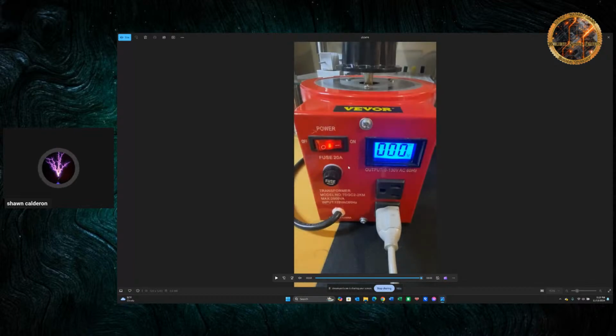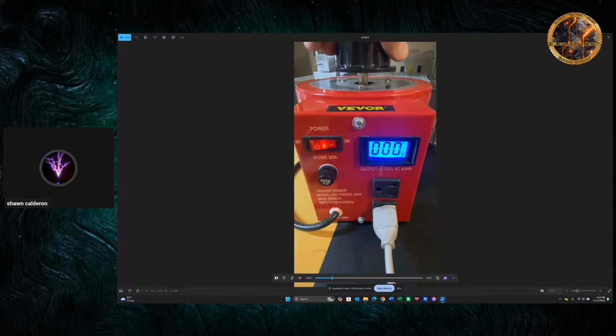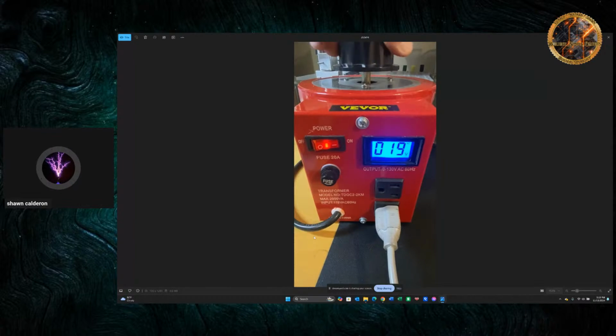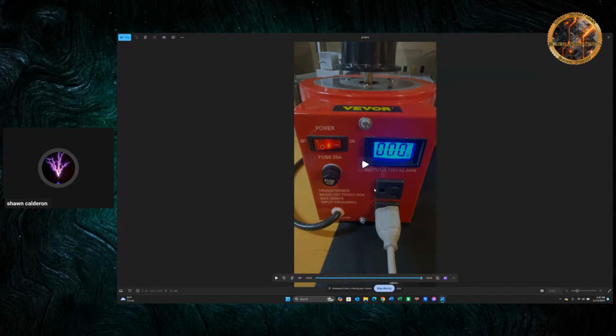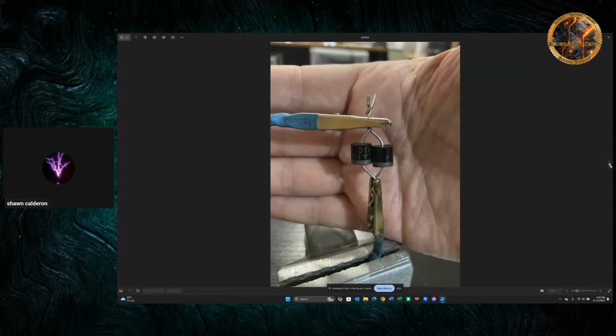Not only that, you're going to destroy a whole bunch more components on your ZVS board. So when you are adding power to your ZVS board on your variac and you just start to turn it and you hear that buzz and feel the resistance, just stop. Don't fry it and find out. But do a couple of things that I'm going to share with you.